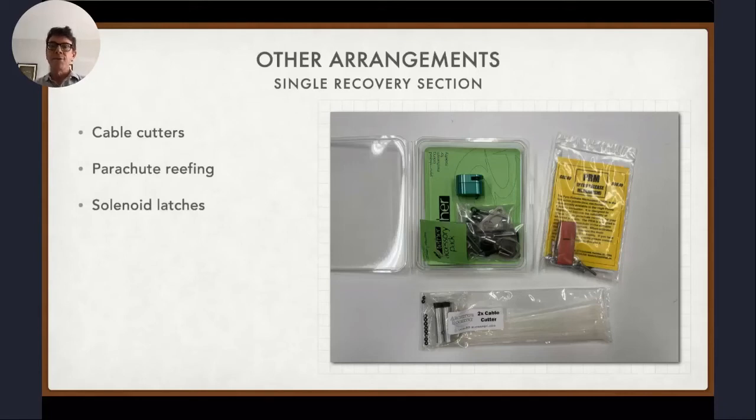And as far as the Jolly Logic, yes, I consider it to be dual deployment. The reason I say that is because there are two events and the rocket descends at different speeds. At apogee, you open up the rocket and it starts descending quickly. By the way, you don't necessarily need to kick out a parachute at apogee. Just the fact that the rocket is no longer as aerodynamically efficient will make it fall more slowly.